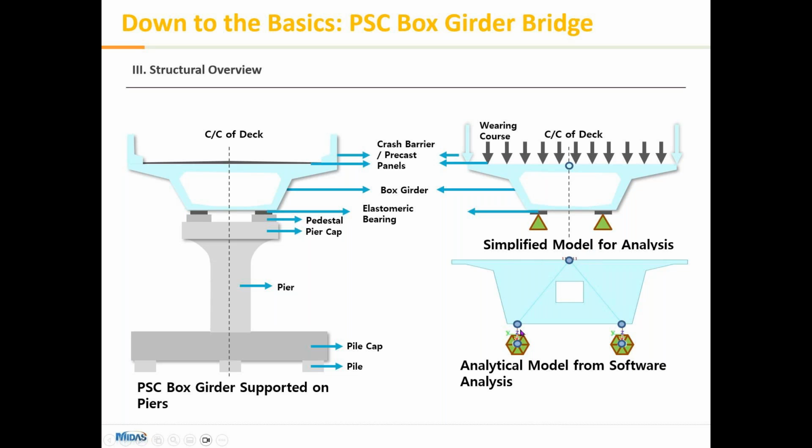We know that these bearings will be modeled as elastic links, okay? And these elastic links will be joined by rigid links, as you can see here. And these will be my supports. Now, what are the elastic links and the rigid links?